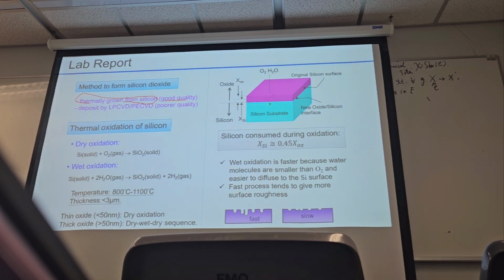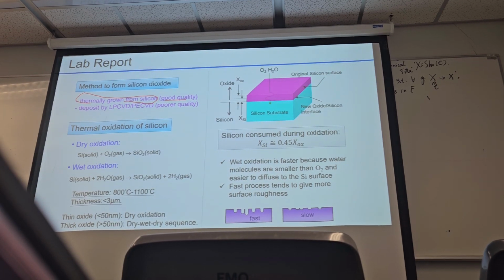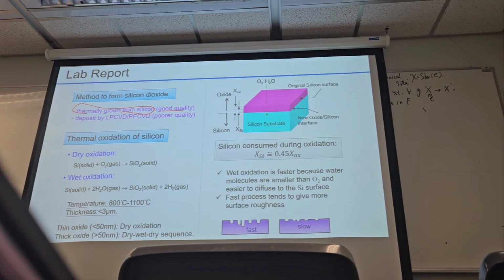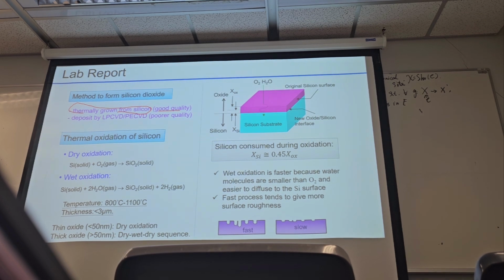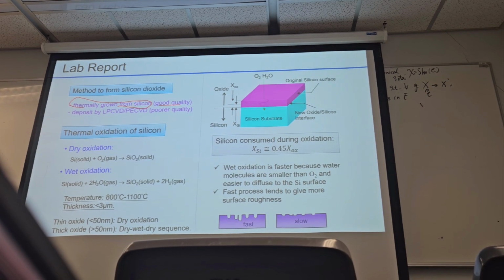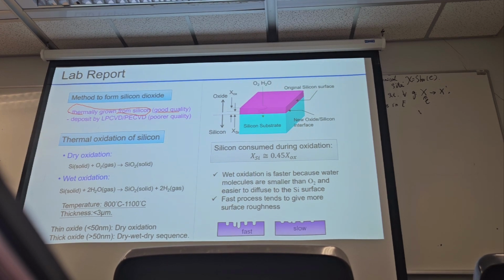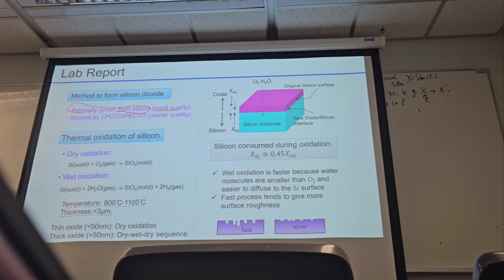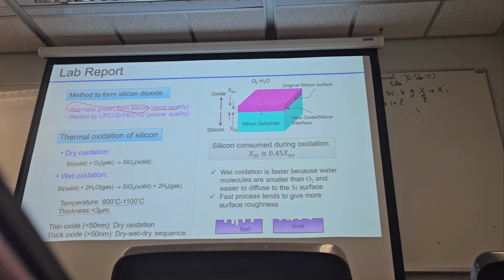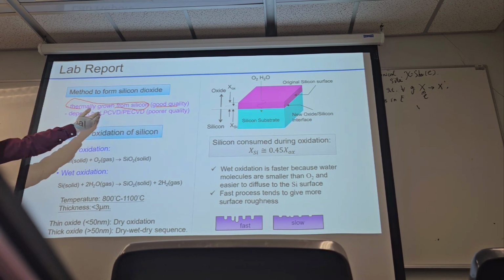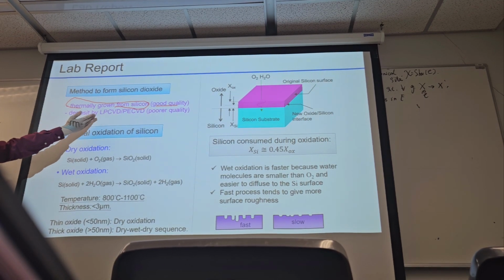So CVD, I think in the lecture quizzes, we also discussed 3 types, right? And here the LPCVD, the PECVD, right? So they do not need to consume the silicon, but they differ based on whether plasma enhanced or not, and also based on the temperature. LPCVD does not need the plasma enhancement. It can be low pressure, but needs high temperature.